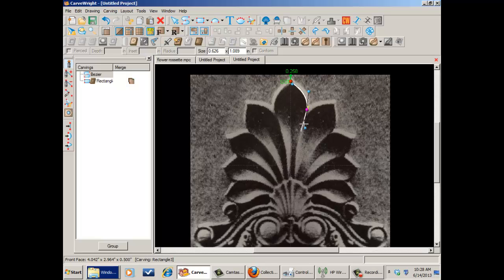Now the next point here, because this was purple, purple means tangent. That means that these two elements are going to be connected as a spline, so it's going to follow the control point that I defined for the last one. So if I put a point down here, it's going to continue that curve around for me, and then put a point. End tool. I can manipulate these together because they are tangent.